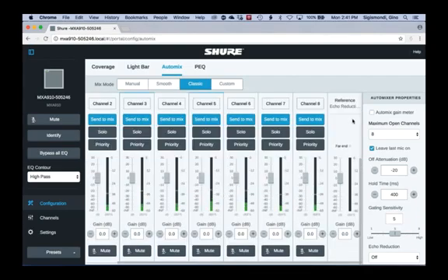Another new feature for those of you that are familiar with using the automatic mix on the 910, we have this echo reduction feature, which can help to prevent echo when you're using it directly with a soft codec or a hard codec without per channel AEC in between. And we still have the same levels of echo reduction, soft, medium, and hard. But now what we've added is a fader and meter here as well. So you can actually see the level that's coming in to your echo reduction reference, and you can adjust that level right here in our software as well. So that's another new update in this 3.0 firmware that's going to be coming out.